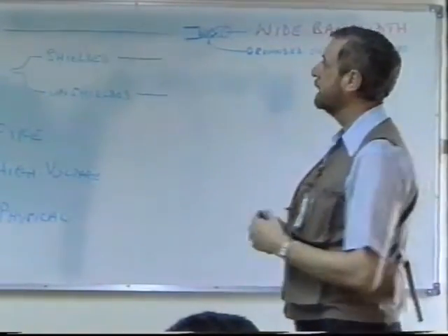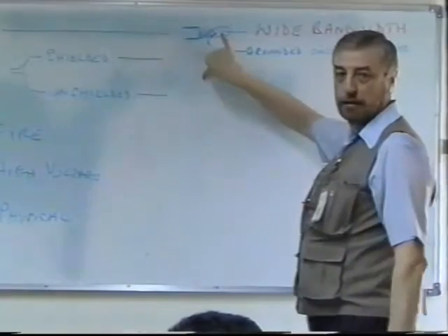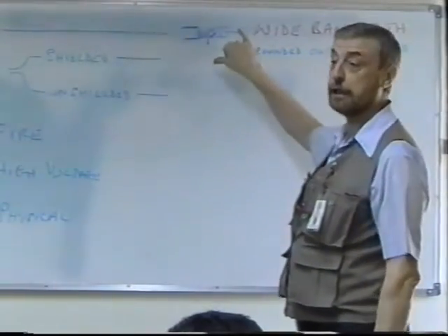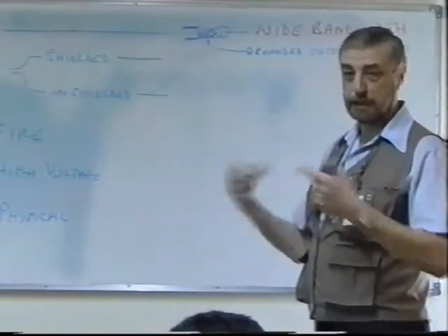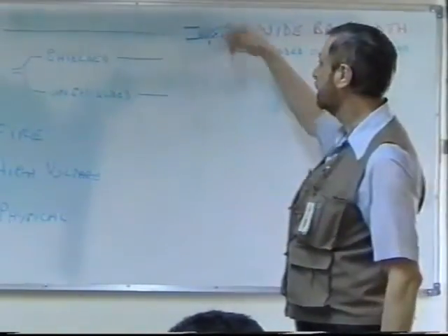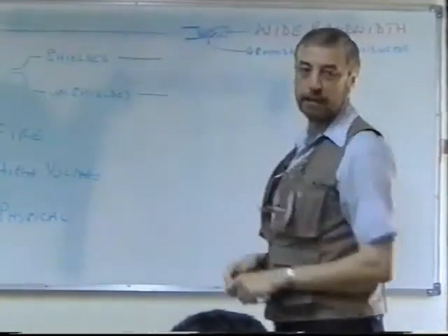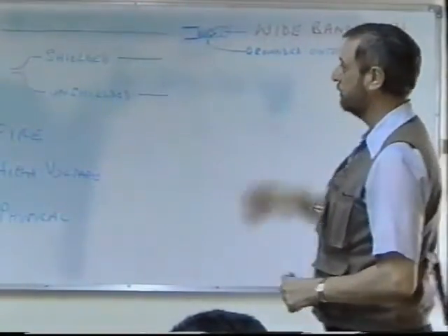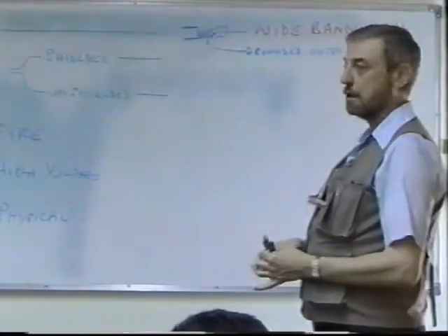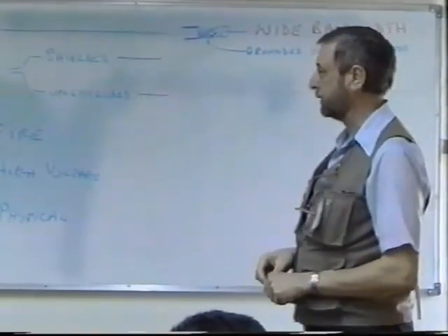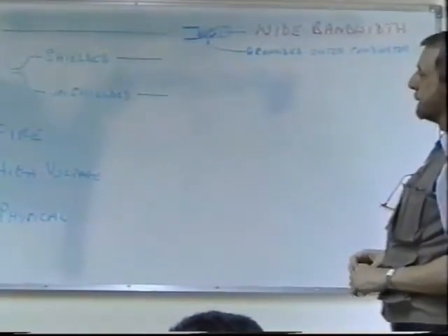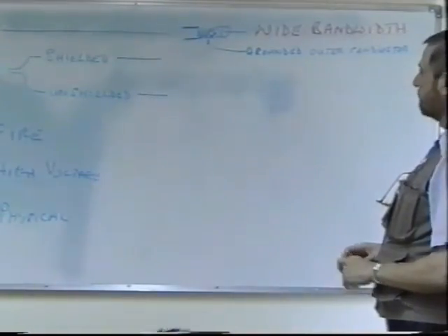So, in this case, the electromagnetic currents that flow in the cable are obviously going to produce electric and magnetic fields. Well, this shielding prevents that field from radiating out and interfering, and also prevents noise from getting in. The result is it gives us a much wider bandwidth than using a straight copper wire. Okay.